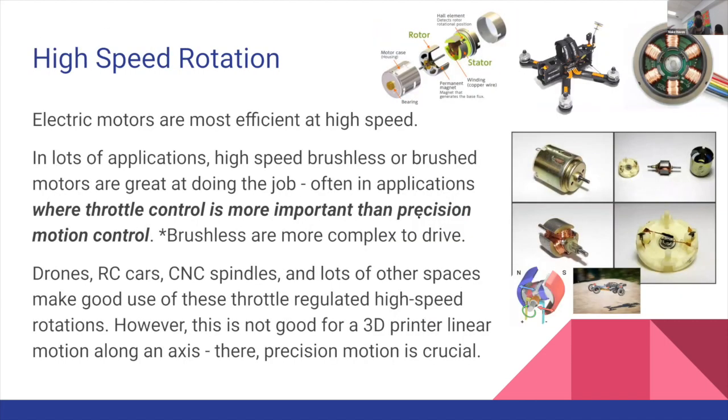If you want to spin something at high speed, there's essentially two ways to do it. You can use a brushless DC motor, like a drone motor, or this hard drive motor. These are different types of motors where the spinny bit is the permanent magnet, and you can see the several wires coming off here. The windings stay in place, and in the middle is where a magnet lives that spins. So the permanent magnet is the spinning part, and you don't need to put electricity to it. You're just applying electricity to the coils on the outside. Same is true for a drone motor. Brushless motors can spin faster because of this. In general, you can make them go a lot faster, but they're more complicated to drive.